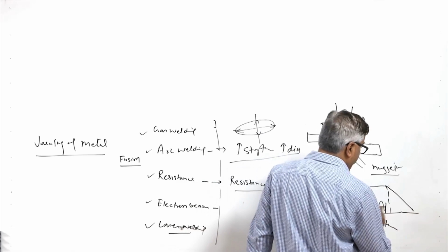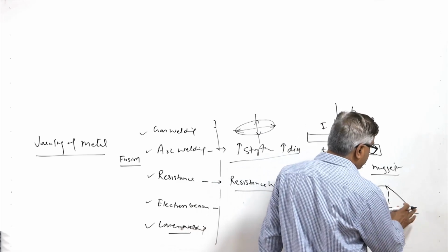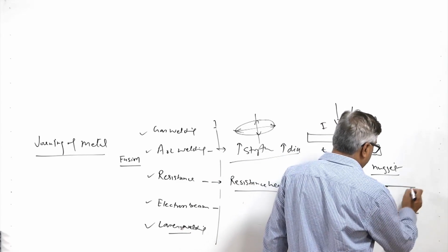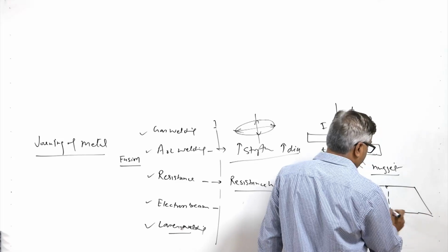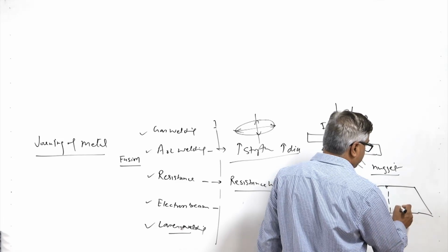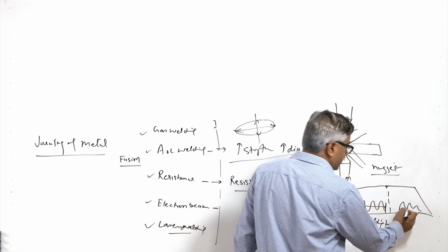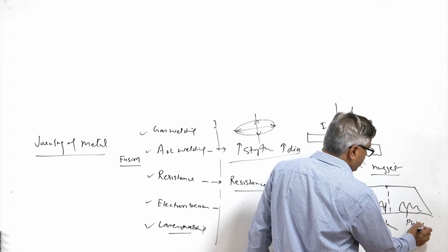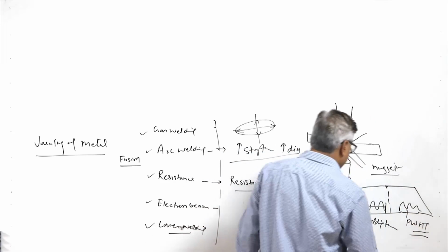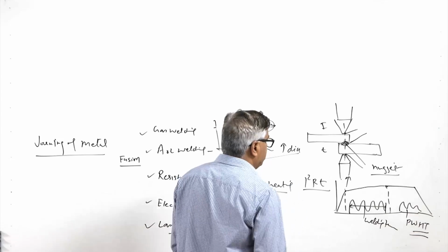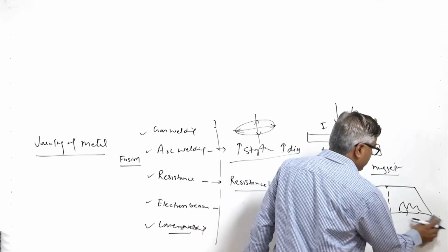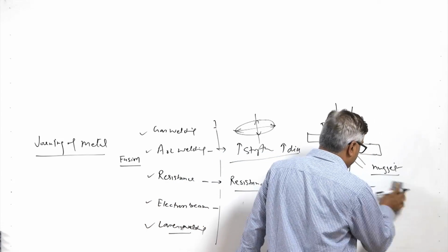Sometimes the pressure is maintained for a much longer period, and then once the solidification is over, the flow of current is started again for one more round for a while, so that post weld heat treatment can be facilitated. But normally the pressure is held constant whenever there is a flow of current.